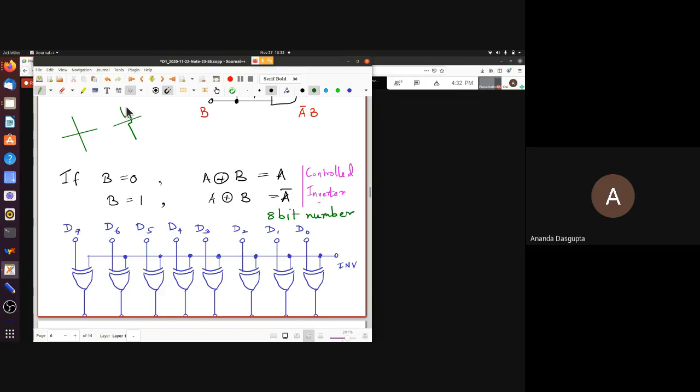But when you are drawing them on a piece of paper, there may be situations where you may have to make the wires cross, even though they're not joined to each other. And of course, the way you draw them is putting a bump. So if you put a bump like this, it means there's no connection. If you have something like this, it means that there is a connection. So there is a connection here. No connection in this case. This is the convention in analog circuits. Note, that's important. It's in analog circuits that you use this convention.